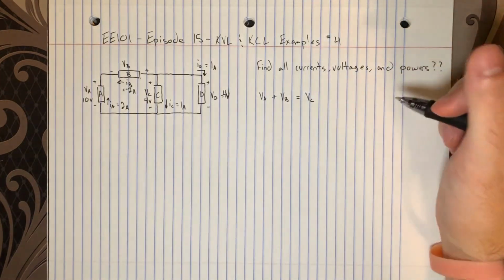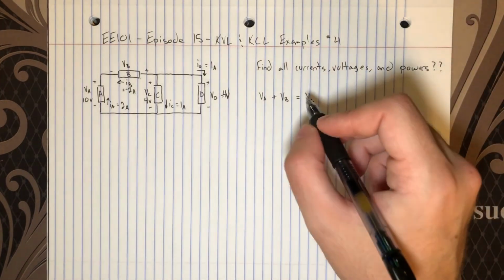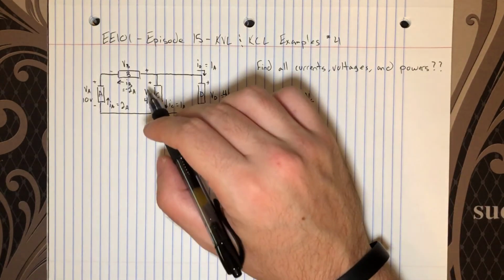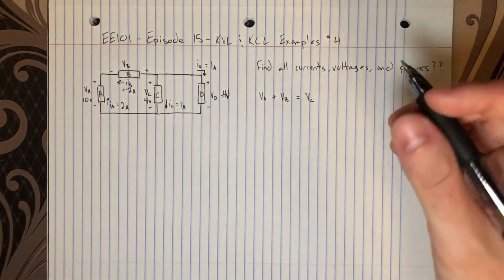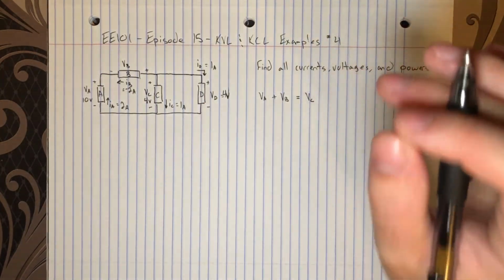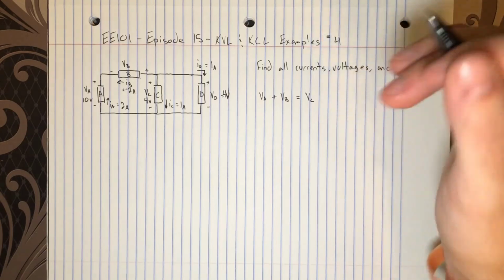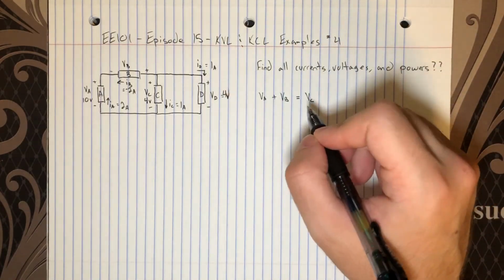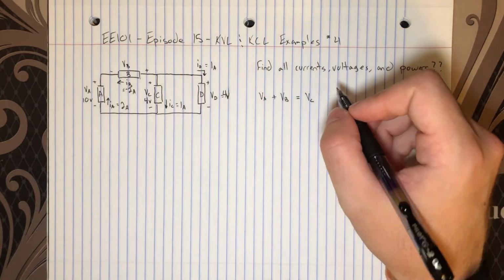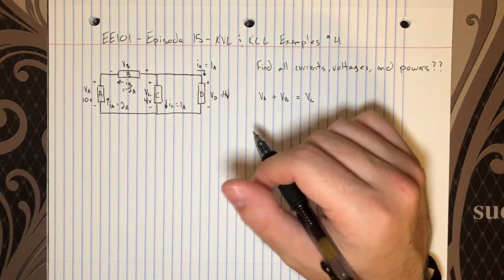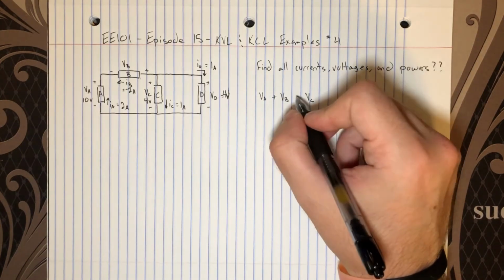Right? That would be the explicit formulation of KVL, where I assign VC a negative because it's the opposite polarity with my agreed upon convention for summing voltages, and then I write that the sum equals 0 because that's the explicit form for KVL. But I'm just taking a shortcut here and saying all these steps up must equal all the steps down because energy is conserved in our circuit. So VA plus VB equals VC.